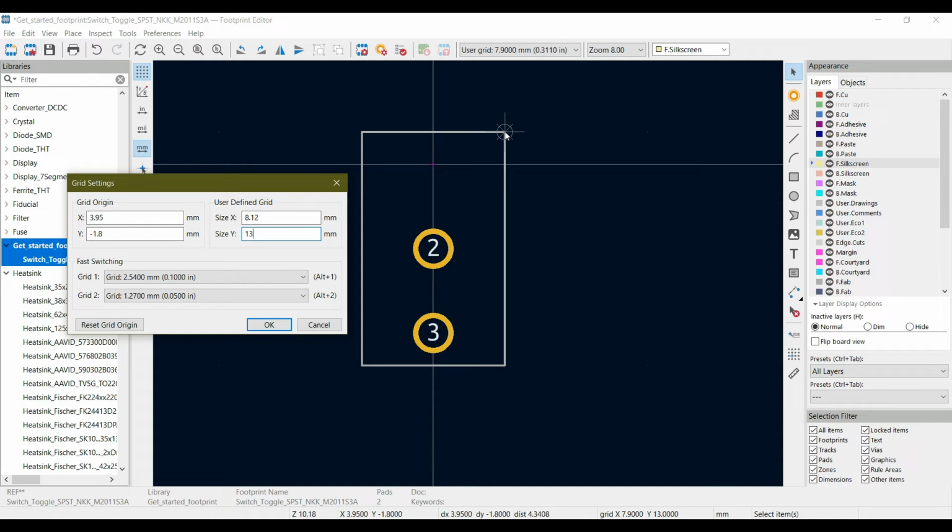Similarly, this dot, or snap to grid, should move a little upward by about 0.11 mm. To increase the size on both sides in the y-axis, we will do plus 2 into 0.11. 2 means on both the sides. So in this way you have changed the grid size of X and the grid size in Y.